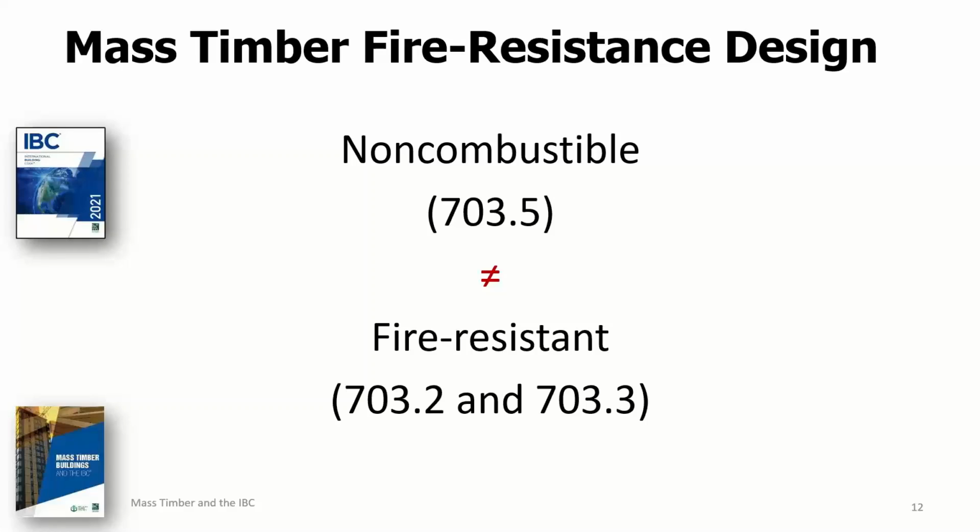They're both very important concepts, but very different in terms of fire safety. Some non-combustible building elements have little or no fire resistance because although they may not burn, they still lose their strength rapidly upon being exposed to fire.